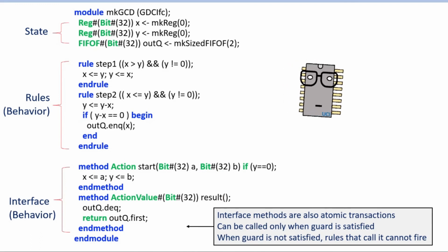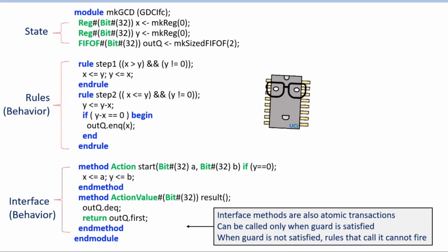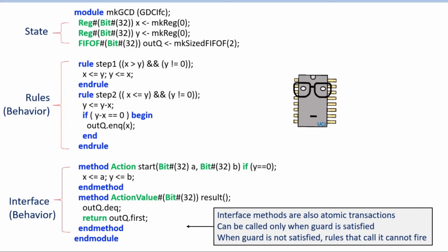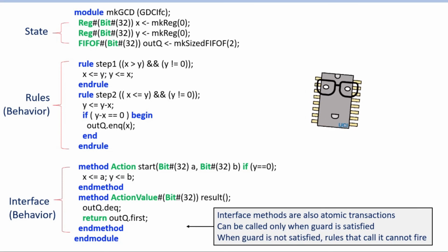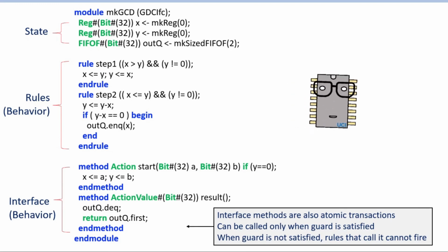One potential caveat of this is that the latency of computing this is variable. And I don't know if for this particular algorithm, we can make the variable latency fixed, for example. If you give a very large number to x and y, or a very large number to x and a small number to y, this algorithm could be taking hundreds, thousands, millions of cycles to finish. And if you instantiate just one of these modules on your FPGA accelerator, I don't know if it's going to be any better than if you just wrote it in software.